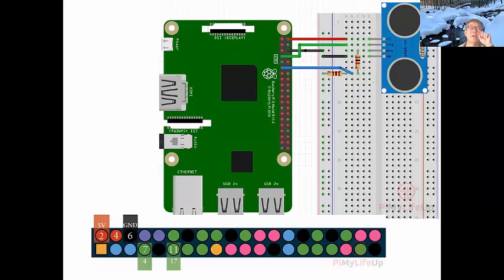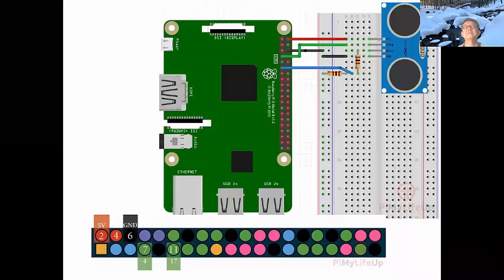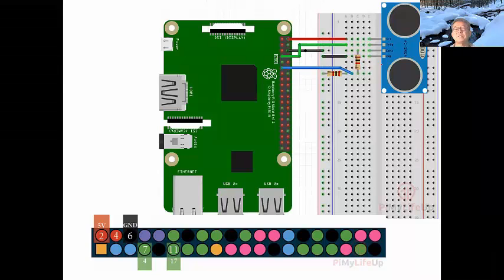You have to wire properly, okay? This ultrasonic distance sensor has 4 pins. Why 4 pins? You can simply think 1 pin for ground, a second pin for power supply, and then two pins left, right? 1 pin is the signal out, and the 4th pin receives the signals.